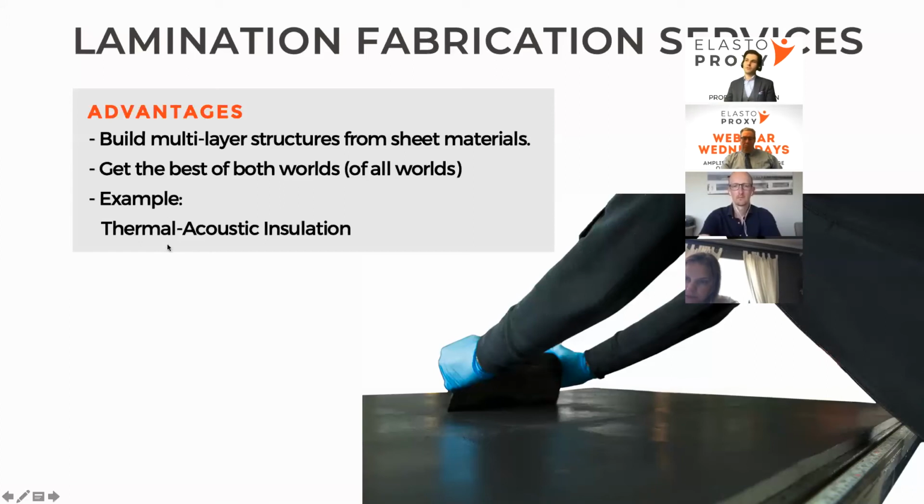One of the examples here, thermal and acoustic insulation: we had a customer that said, we want to be able to keep the noise inside a compartment. However, there's a high heat source where this compartment is. So we have to take that into consideration. We have to figure out, is it low or high frequency sound? And we were able to determine that it's a bit of both. So we had to take that into consideration when we were coming up with this sandwich, as we call it internally.